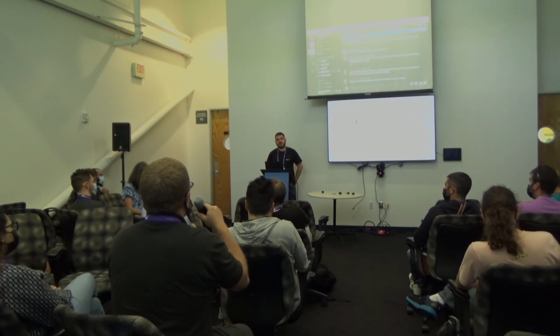So no, we didn't focus on the performance in the first place, because openAMP is actually used for handling all the additional or non-standard instructions. Non-standard in a way that we don't know about them in Zephyr, so we just send them to the application in Linux using this remoteproc openAMP way.